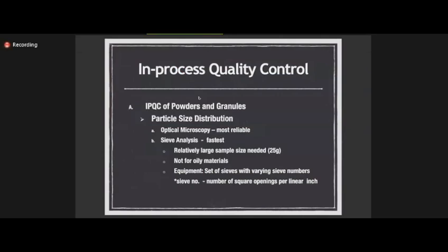The most reliable method is optical microscopy. However, this is very time-consuming because you look at the particles one by one through the microscope. So the fastest would be the sieve analysis. In the USP, the acceptable method is this sieve analysis, using your sieve.